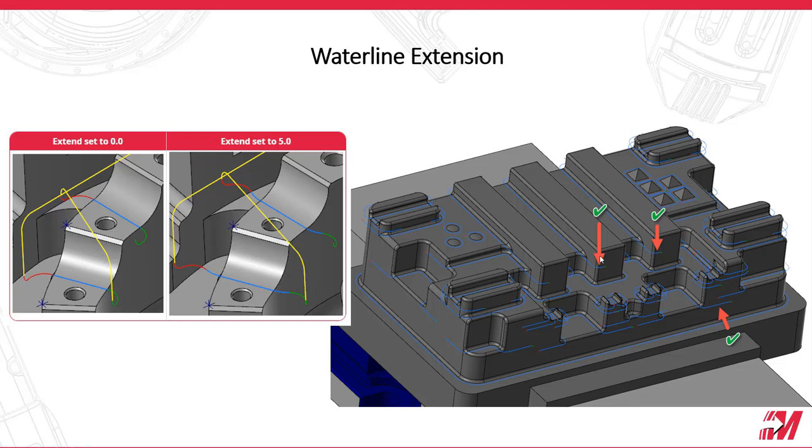I mean, if we take a look at this and specifically this location. Typically, I want to run my end mill pass kind of like it's going there. I don't want to end there because I may have a witness mark there. But if I can go ahead and run that past like it's showing, then I have that much better of a chance of blending that wall out and not having any witness marks at all on there.